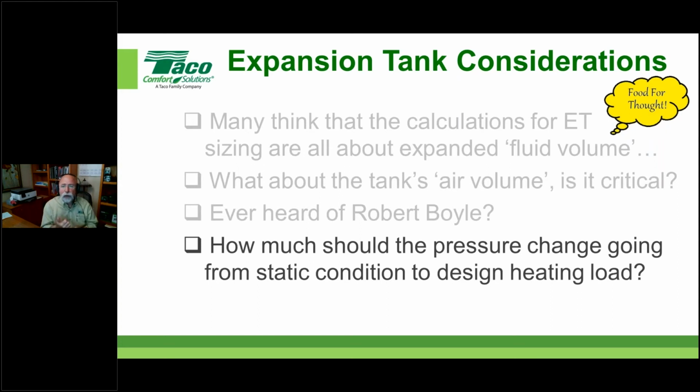So how much should the pressure change? Going from a static condition, when you first set the system up and there's no power, you've done your purge, you've done your fill, all that stuff, and before the system heats up to the point where it's running at a design load condition. So how much should the pressure change?